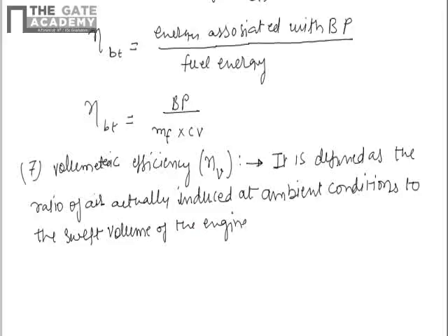So I will again repeat, the volumetric efficiency is nothing but the ratio of the air actually induced at the ambient conditions to the swept volume of the engine.